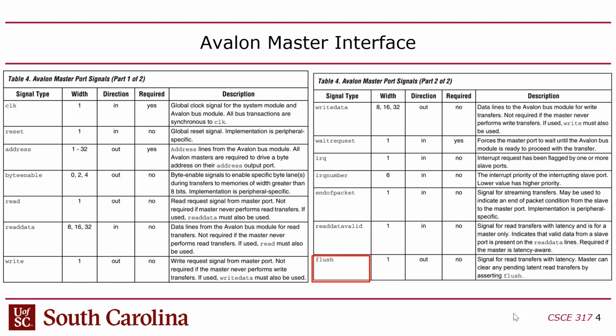But the data width of the bus can be set. If it's more than 8 bits, then you have a problem if you only want to send 8 bits, right? So if I have a 32-bit data bus and only want to send 8 bits, you would need this byte enable, which allows you to tell the slave, look, I'm sending 32 bits because I have to, because it's a parallel bus, but only the low order 8 bits represent the data I want to send you.